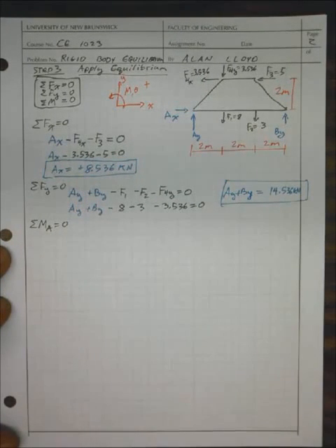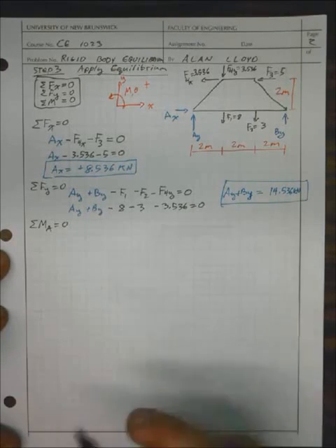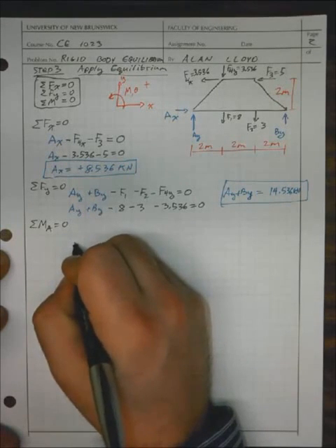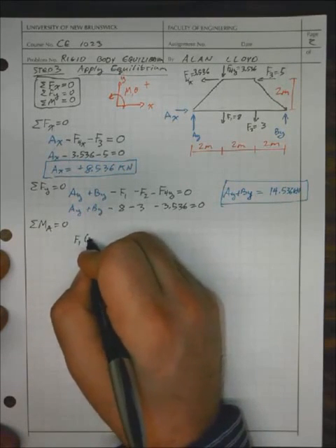So here we're going to be looking at force times distance. And remember, the distance is orthogonal to the line of force that passes through the point at which we're taking the moment. In other words, the perpendicular distance to the point about which we're taking the moment. To do that, let's begin with putting in our values, and then we're going to assign a sign to it.